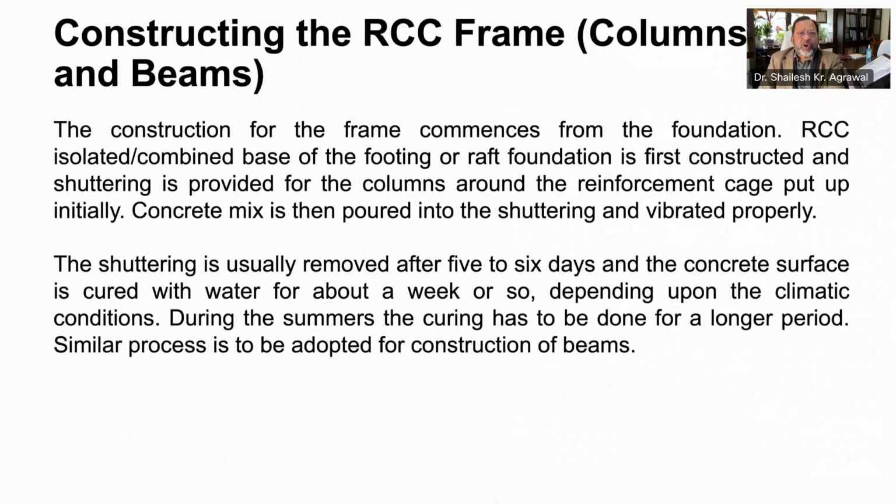The construction of RCC frame starts from foundation, as I explained to you in previous digest. RCC isolated or combined footing or raft footing, as the case may be, is first constructed, and then shuttering is provided for columns around the reinforcement cage, which is put up initially.